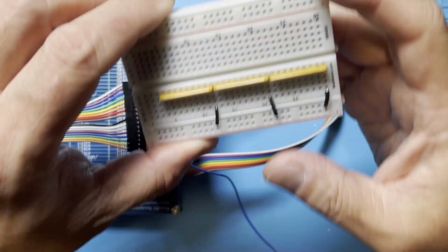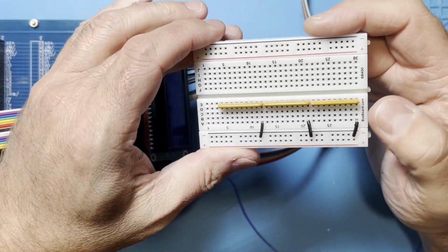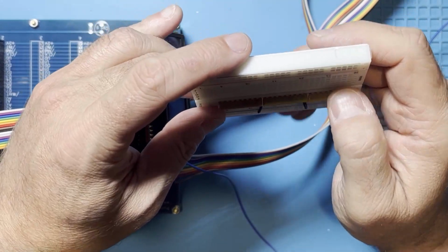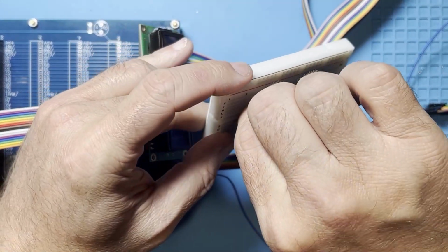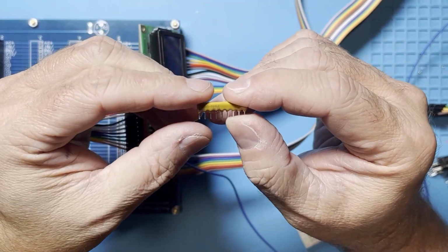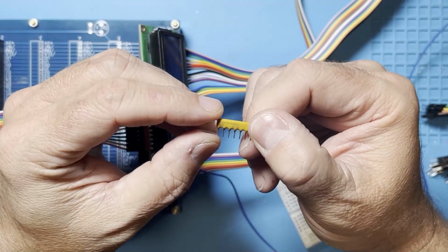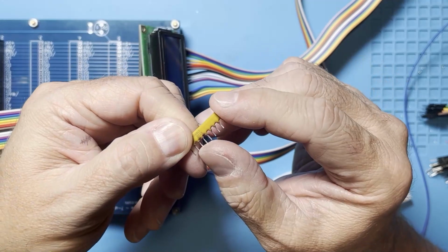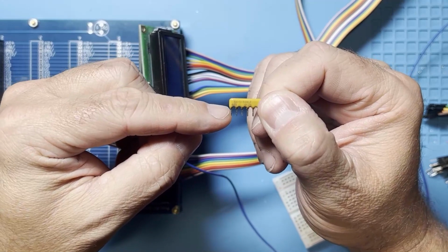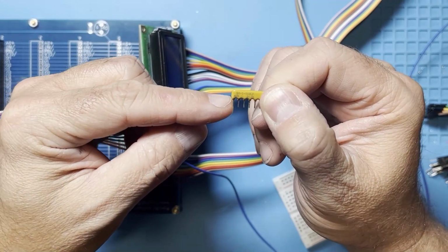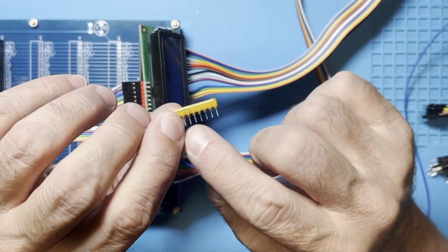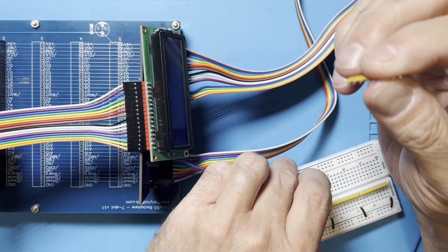Okay, so here I've got a little breadboard and all I've got is some resistor arrays on it, and they're 10K resistor arrays. And what resistor arrays are is, let me pull this out here and kind of demonstrate. This has 9 legs on it. 8 of those legs are connected to resistors, and all of those resistors are connected to this 9th pin right here, which is the ground. So it's a really convenient, space-saving way to use the resistor.